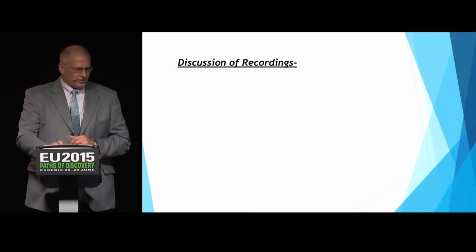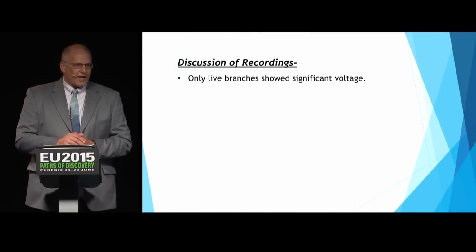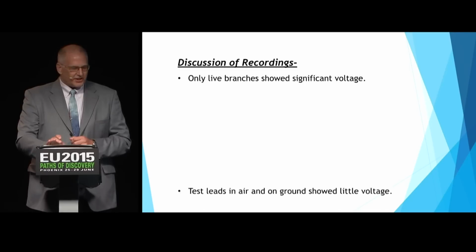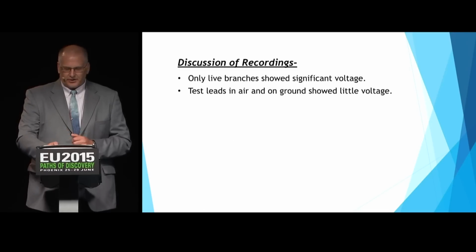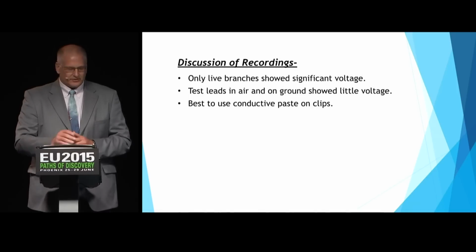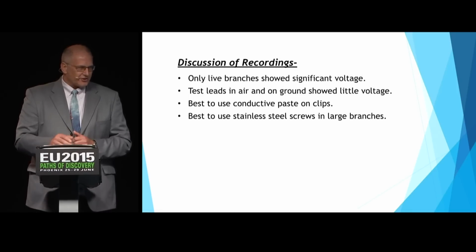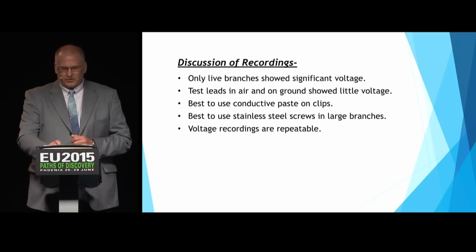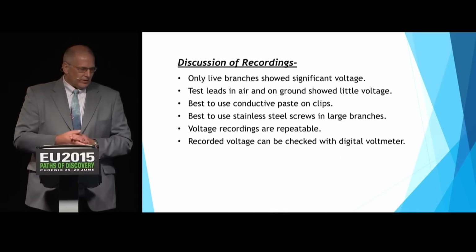Discussion of recordings. Only live branches showed significant voltage. The test leads in the air on the ground showed little voltage. It's best to use conductive paste on the clips. It's best to use stainless steel screws in the large branches and trunk. The voltage recordings are repeatable. The recorded voltage can be checked with a digital voltmeter.